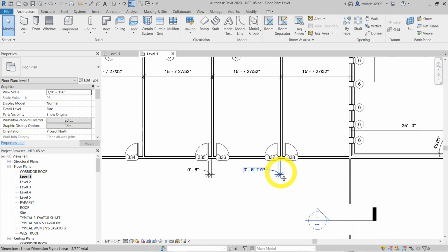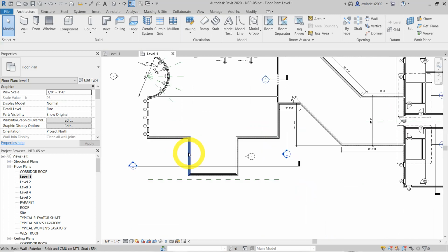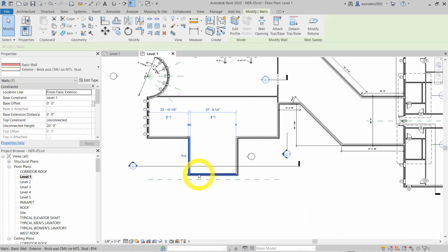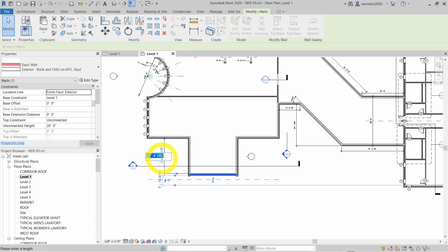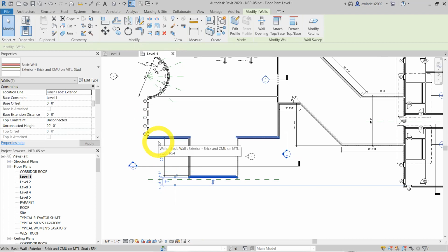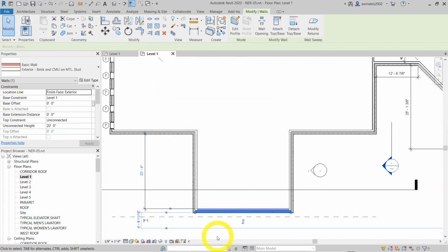It's really on the page 257. So if we select this, saying make that permanent or not, but mostly it wants us to change this to 22 feet, space 6 inches. Enter. So it stays that. As the new layout of that wall, I made it permanent.